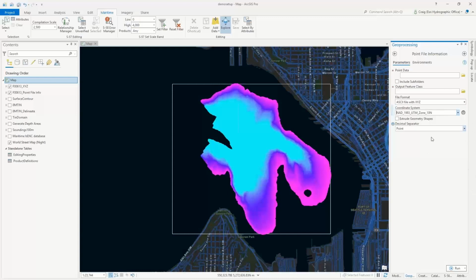With Python, if you had it in a TXT or an XML, you could extract that information and pass it to this parameter. So that's one way in which you might want to use Python versus ModelBuilder. Sometimes I'll build something in ModelBuilder, and then I'll give it to one of the Python people on our team, and they'll make a Python script tool out of it.